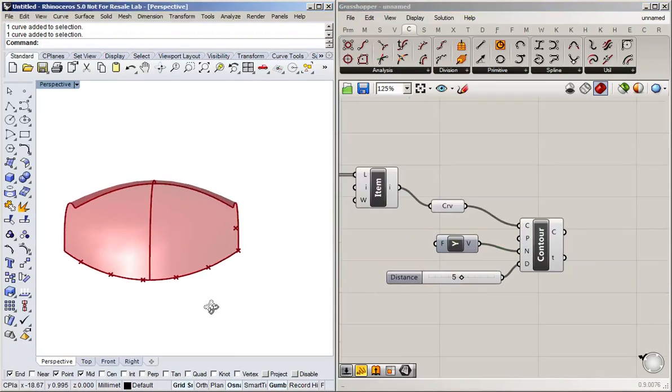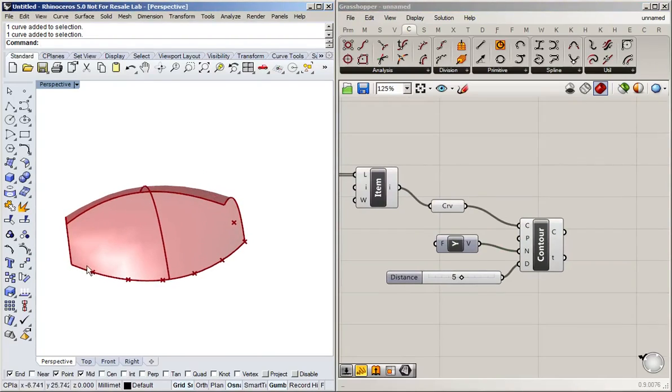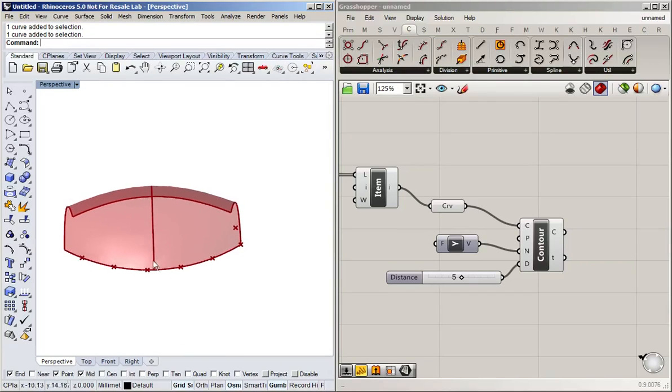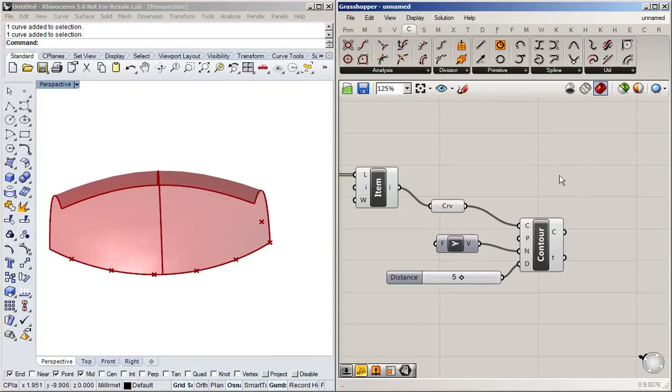And of course, it's like all the other divide distance things, this last segment is probably going to be shorter than the desired distance of 5 here. So you'd actually have to go and measure the distance between this point and the end of your geometry, figure out how many segments you want, and then determine what the distance has to be, or some other way of getting this shortest little last bit problem solved. All right, well, that's not what we're going to talk about today.